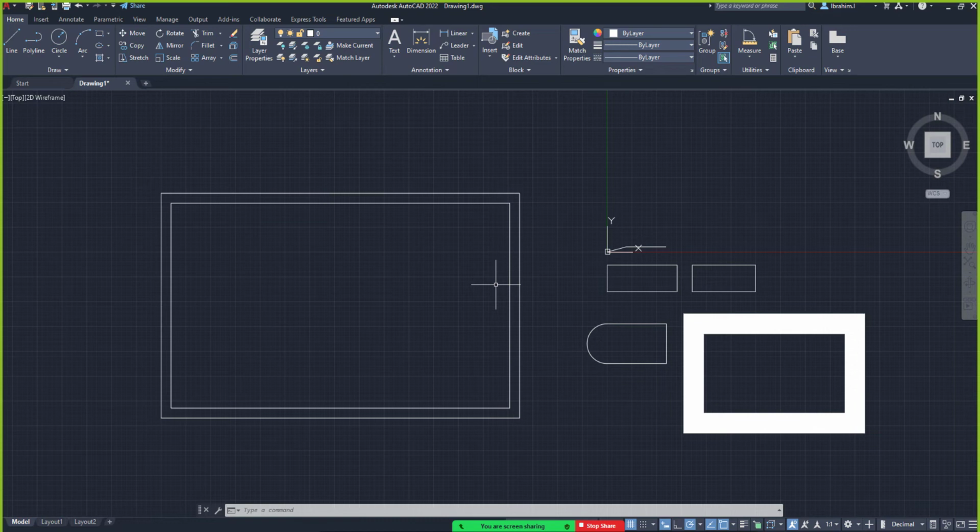No. Instead of it to just give a shaded color like this, no. Using your polyline width command, it will always be shaded by default. This is different from going to a line and adding line width to it. I can select this line and add a line width of 5 to it. That's another thing entirely. But by default, immediately you add width when you create your polyline width, it will be shaded by default like this.